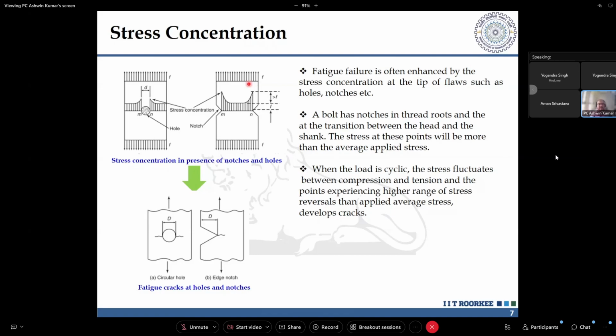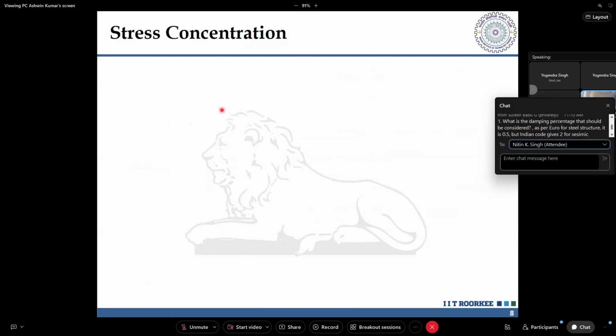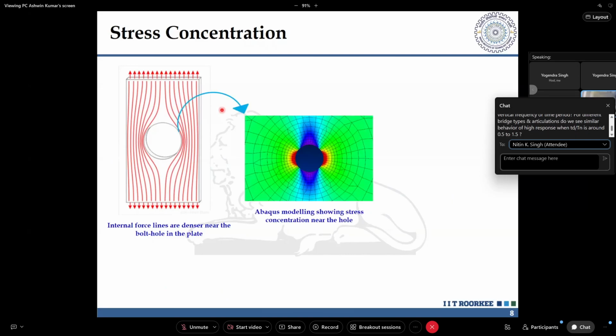But if I take my stress range based on the maximum stress and the minimum stress at this particular location, then it may throw off that the material, or the assembly, is not good enough, right? Sometimes you are not able to understand what the stress range is that is coming in the material. You need to do an FEM analysis to understand.